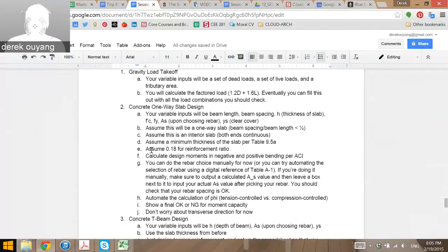But you've got your gravity load sheet. It's your first module, which just exists on its own. You feed into it all your dead load and live load things. The factors you consider here would probably for now just be this one. But just know that if you build spreadsheets for lateral designs at any point, you would obviously consider additional ones. So you consider it, and then out comes really this, which let's say is in psf, pounds per square foot on a given floor plate. Okay? So that's all you really get for now out of this gravity load spreadsheet. You go to your next one, and we have one-way slab design.